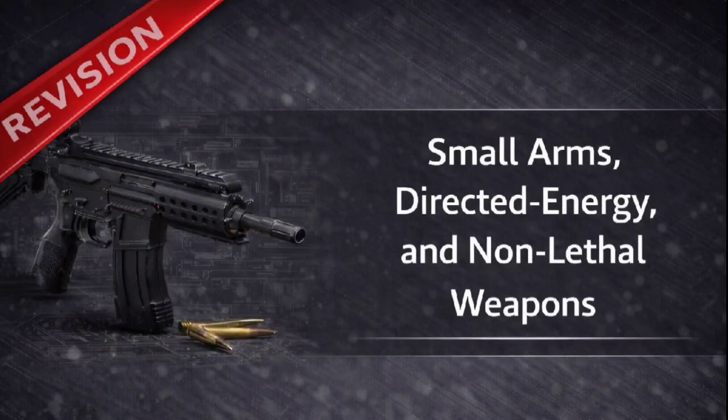Next, we have delayed blowback, also called hesitation blowback. Delayed blowback introduces some mechanical complexity in order to reduce the necessary mass. It uses specific mechanical parts, usually levers or rollers, that are forced into recesses in the receiver. And they hold it shut for a moment. They hold the breech block shut for a minute, controlled fraction of a second. The delaying force is at its greatest precisely when the gas pressure is highest, and it tapers off as the pressure drops. The efficiency is immense. How immense? A successful delayed blowback design can reduce the necessary breech block weight to just 1/16 of the weight required for a comparable simple blowback system.